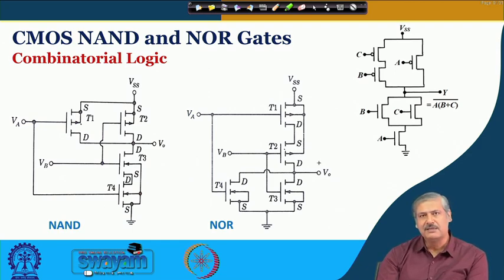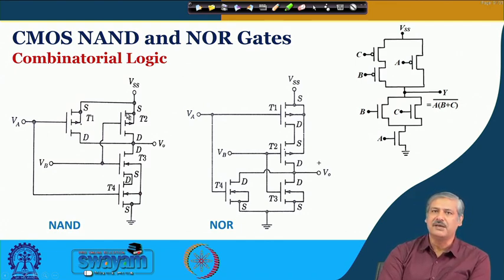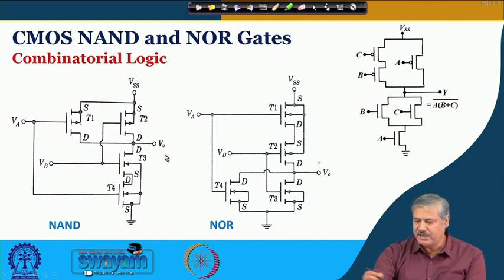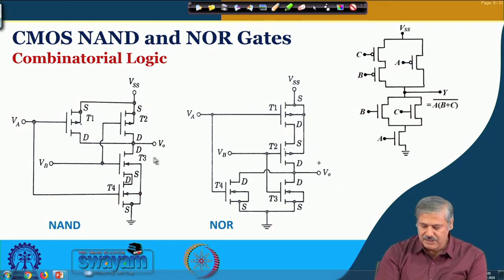So, for NAND gate development, we have two NMOS in series and the corresponding PMOSs are in parallel. Okay. So, any one of them is low. What is happening? Say VA is 0. So, this is in series, so this path will not be there. This path is blocked. Say this is blocked by this one, right?